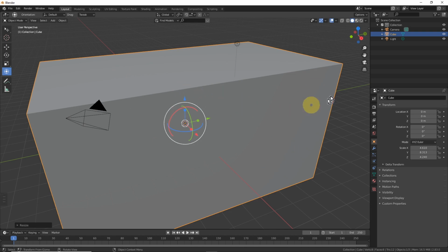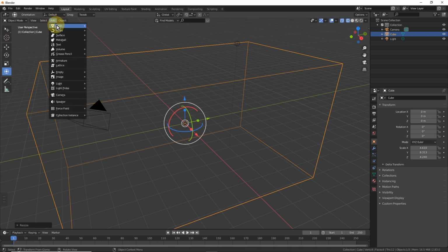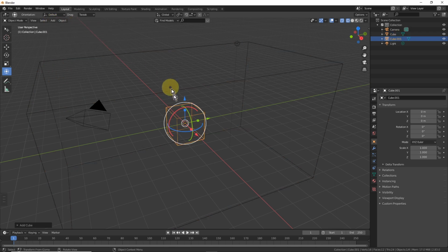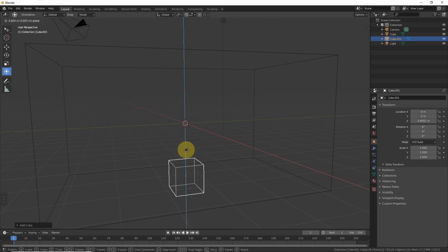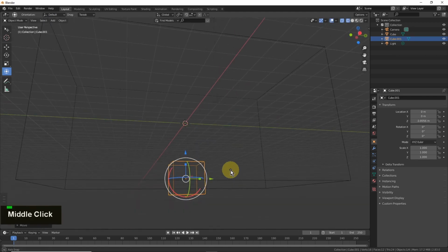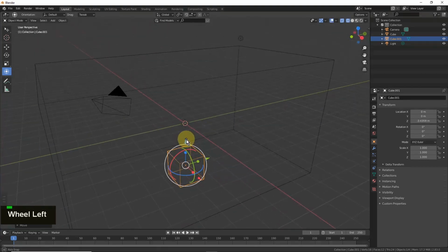So I'll do that, and next we toggle wireframe mode so that we can see inside it, because we're going to position another cube inside it right here. Gonna push it all the way down here, so the second cube acts as a deflector for the liquid that we're gonna simulate, so that something's happening in here and it's not so boring.